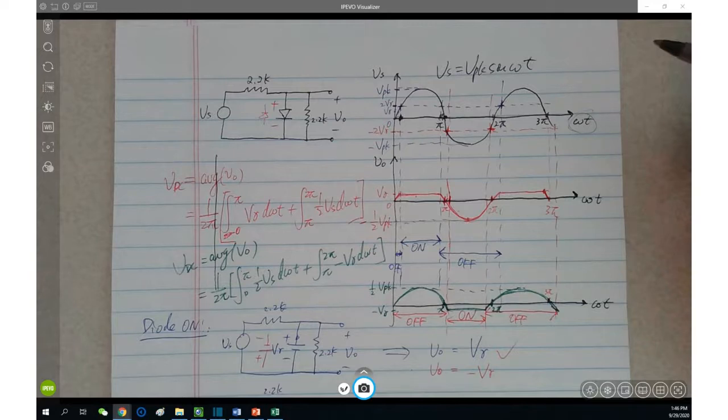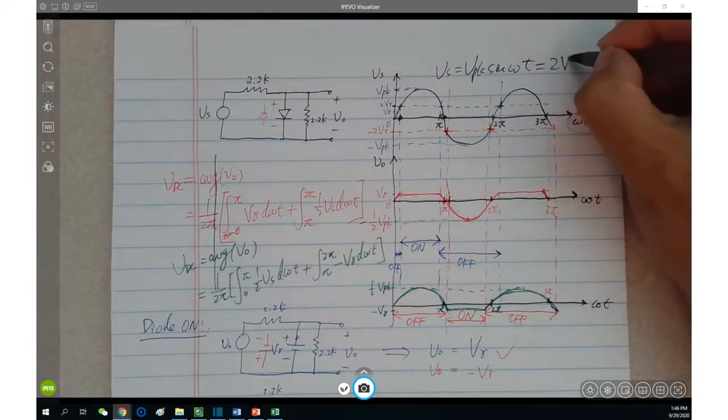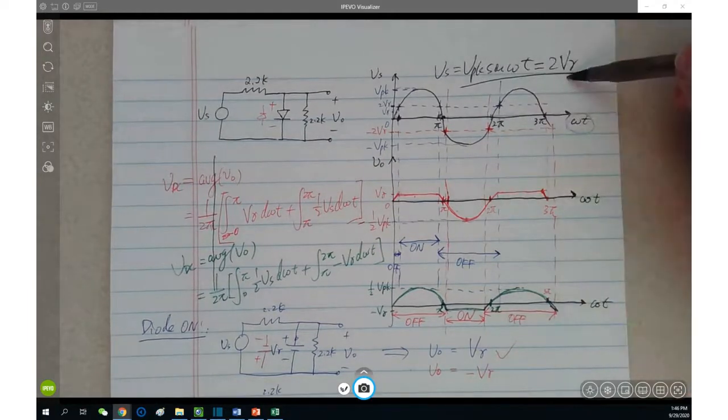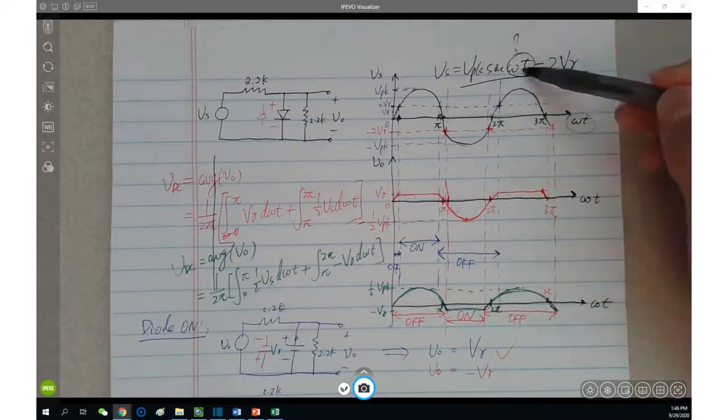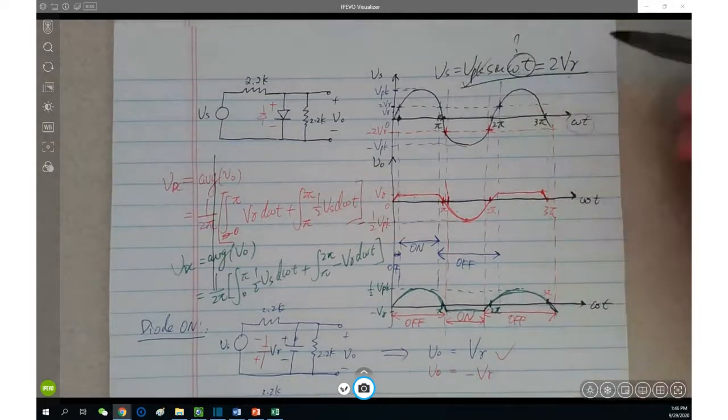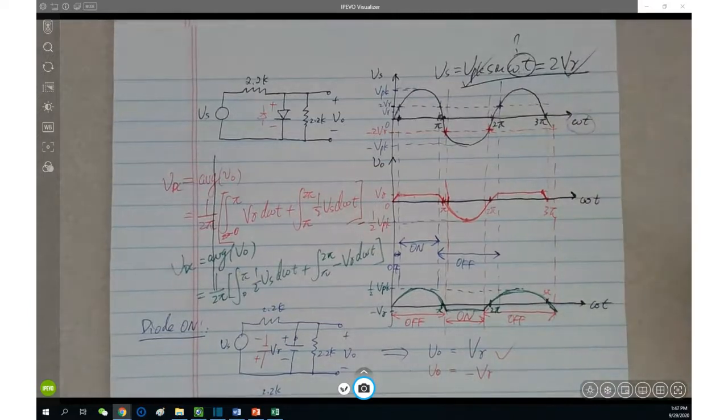By observing this, yeah, go ahead. You would substitute 2V gamma for Vs in that equation you've got right above the graph. Oh, perfect. Here we go. One equation, one unknown. Looking for this unknown. Done. Because V peak is something specified, and V gamma is something we know. Exactly right. Looking for this angle position, which is nothing but this point and this point. Very good. Great answer from Shay.